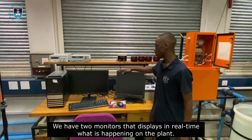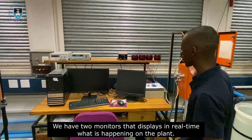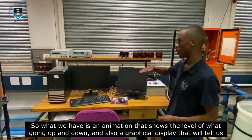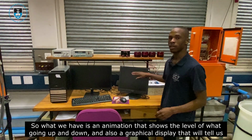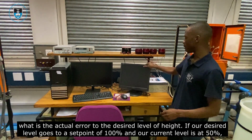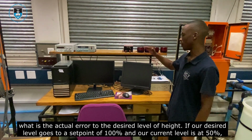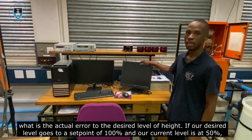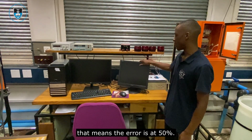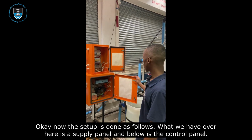We have two monitors that display in real time what's happening on the plant. What we have is an animation that shows the level of water going up and down, and also a graphical display that will tell us the actual error relative to the desired level of height. If our desired level goes to a set point of 100% and our current level is at 50%, that means the error is at 50%.